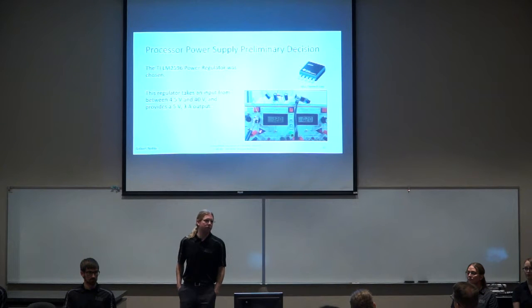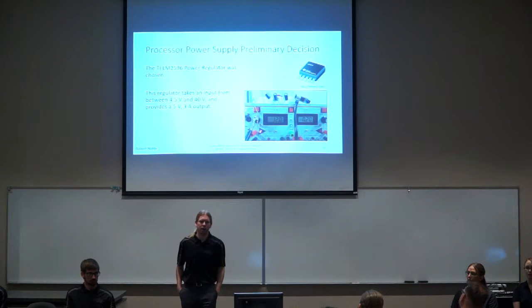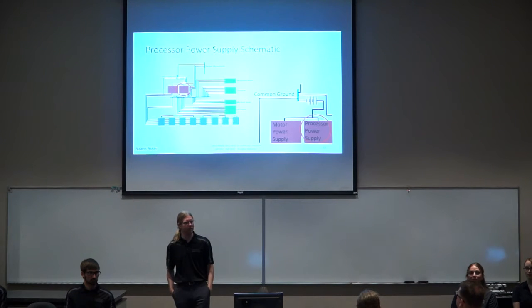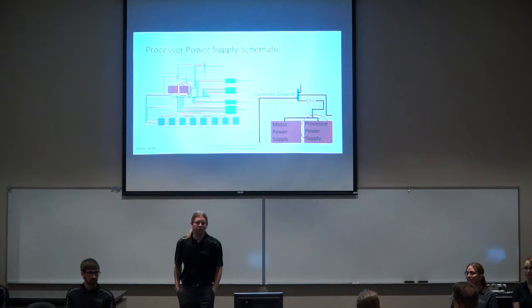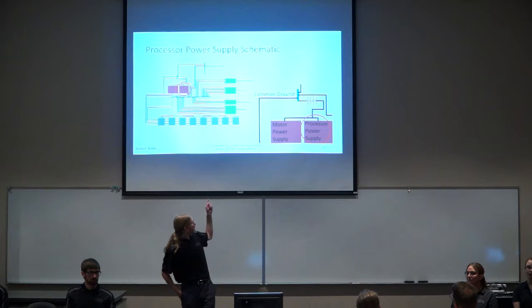As seen in the picture, I was able to prototype the board, since we had the components nearby to prototype it, and I was able to supply up to 12 volts to the voltage regulator. I was not able to go higher because I was using a transistor to spoof a diode, and the transistor could only take up to the 12 volts. From this circuit diagram, the processor power supply is connected from the battery to the BeagleBone Black as outlined in blue.